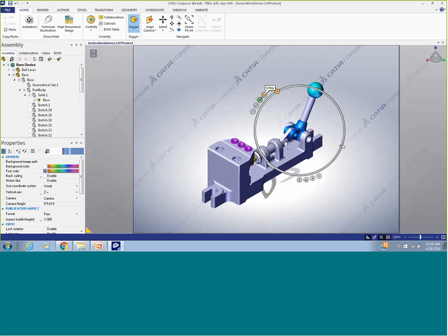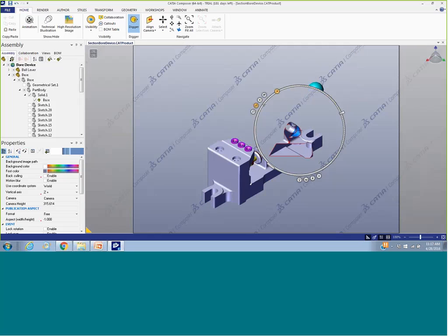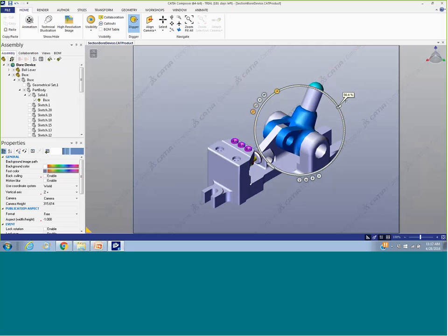Now, there are other modes over here. I could go through and do X-ray mode, and I could then go through and make an X-ray and X-rays back into the model as I drag the handle. I could also come over here and do cutting plane. I could push a cutting plane parallel to the screen back through the part. And then there's even a button over here for going through and zooming up. Okay, I want to blow up this area here and see this better.